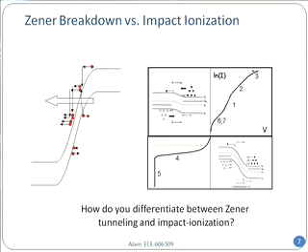Region 6 is trap assisted recombination in the forward side. And again, just like number 2, region 6 has half the slope of the diffusion regime, because electron and hole must be equal to each other before they recombine. So if you see a half slope region at early low voltage, then you know your junction is horrible.